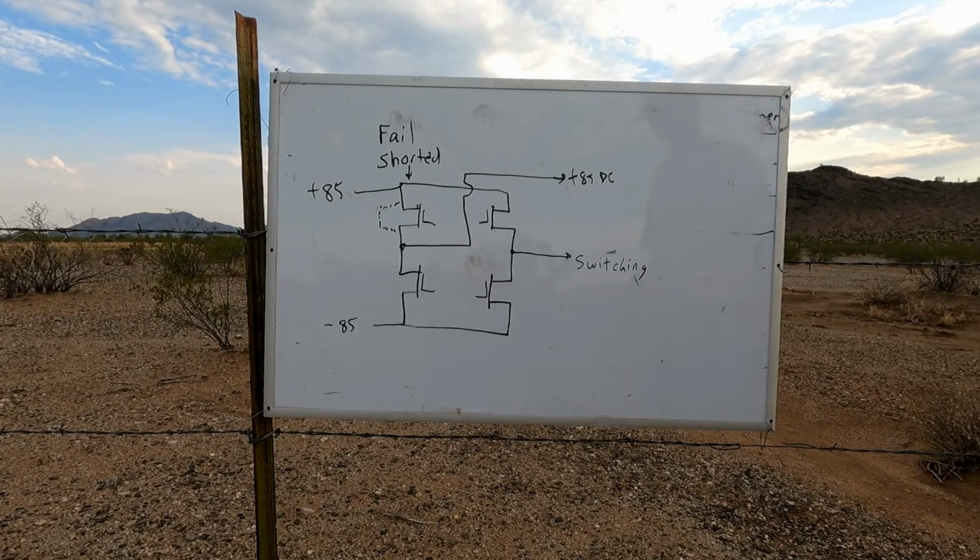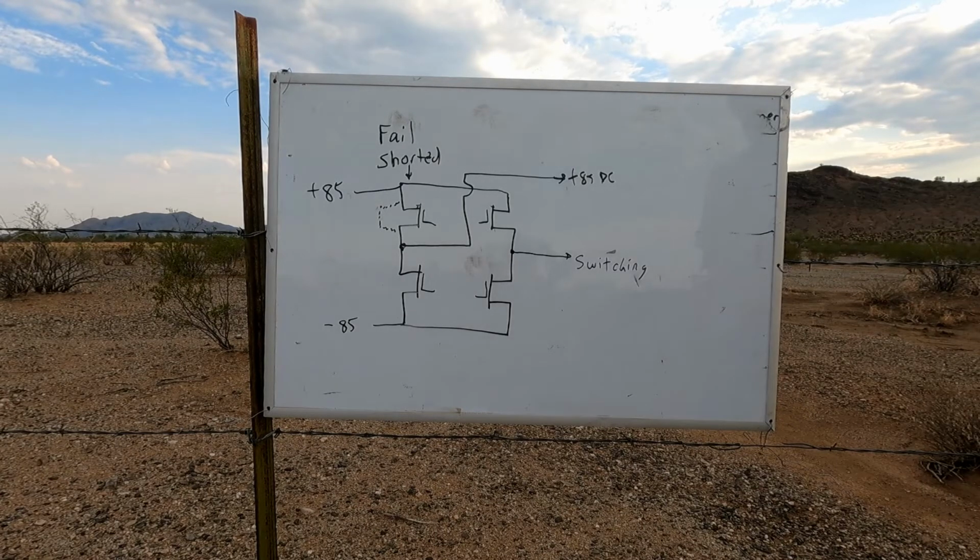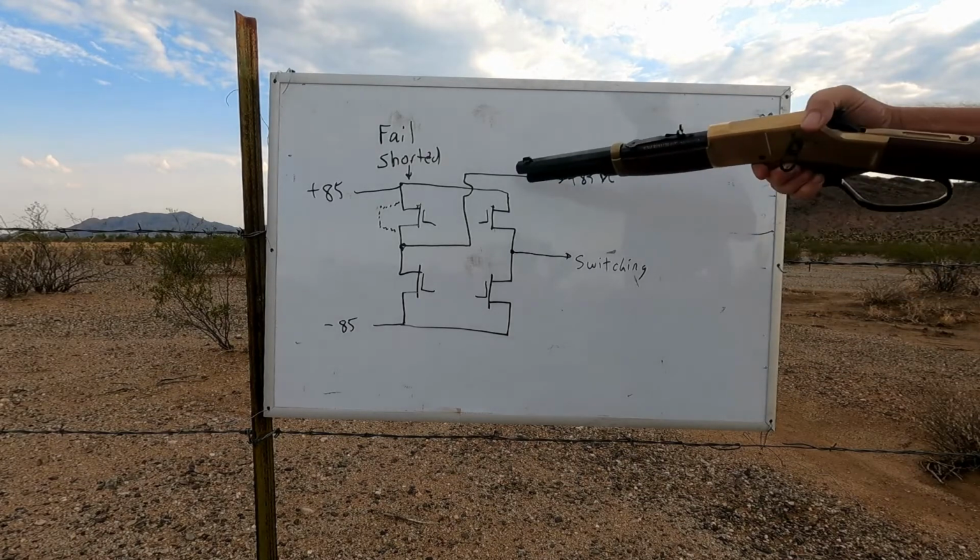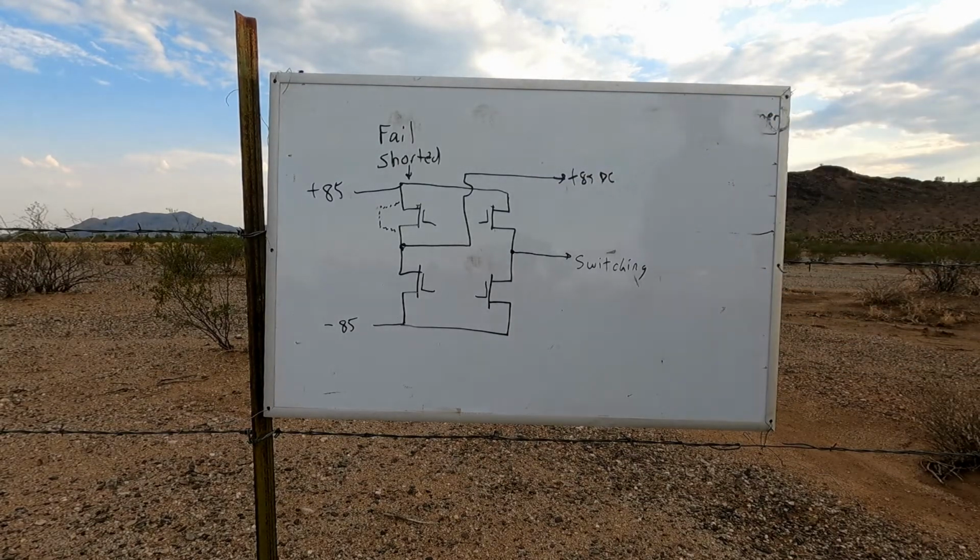And so there's nothing left in this circuit to stop the current flowing under this fault condition. I personally have had this happen. I'm inside the house, I got a short on an AC outlet, it failed the inverter, and I didn't even realize that it had failed and was outputting DC until I smelled some nearby electronics getting hot, and luckily I went out and disconnected the inverter before it led to any damage. And the problem is the current just isn't high enough to trip a circuit breaker.